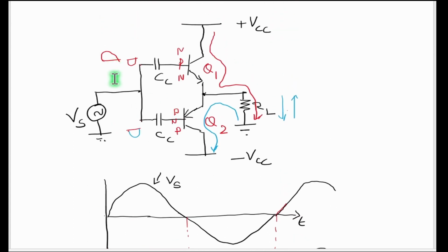In this circuit, when you give positive voltage, the transistor Q1 will not conduct immediately because there will be cut-in voltage 0.2 or 0.3 volts. If the input rises beyond 0.3 volts, then only Q1 will start to conduct.